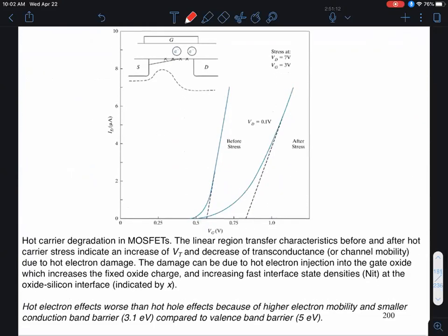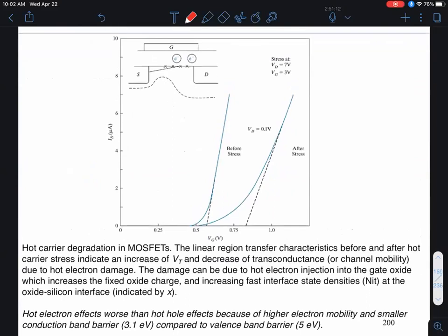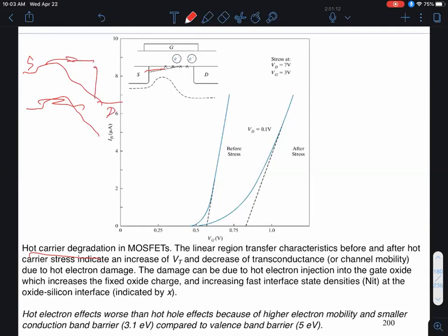But as I said, because the power supply voltage is not scaling to keep the electric fields constant, you can get these hot electron effects or other short channel effects. So the hot electron degradation is shown in this particular figure. What I'm showing is these electrons are being injected from the source, traveling towards the drain. If you look at the band diagram, that's my source end, that's my drain end. These electrons are going in, they're getting hotter and hotter. So here I have hot electrons, okay? And if it gets hot enough, they can be injected into the oxide.